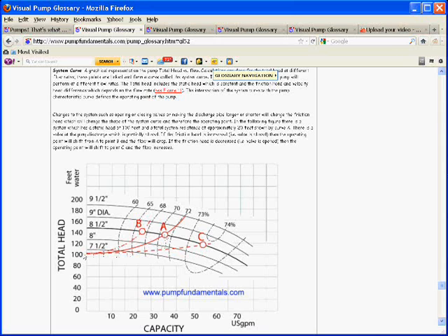The other point you can see here, right here on the axis, this is the static head right here. Because there's no flow, zero flow, the static head in this particular case is 100. Then we calculate how much friction head do I have to operate at 35? So that gives me the other little bit, and then I have that point A.